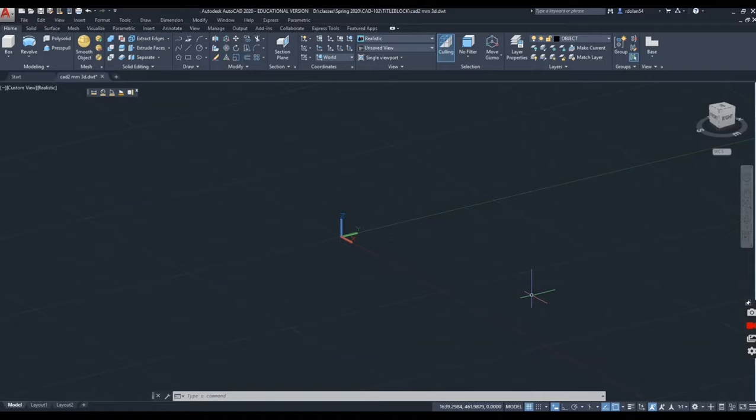Okay, I'm going to look at the bracket. Okay, the bracket, we're going to draw the front view. Make sure that you're in your template, the right template. Make sure you go up to view and change it to third angle projection. Type in perspective and equals 0. I'm not going to tell you all that again. Alright, so I'm going to go to the front view. So I'll go up here to front.